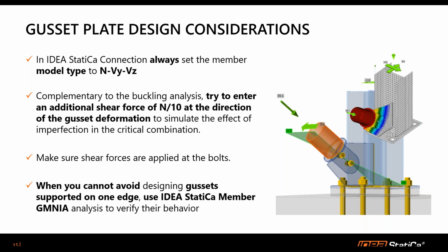Now, when you want to perform a full design, but you don't want to go into IDEA StatiCa Member, what you can do is enter an additional shear force to the case that's critical for the design.